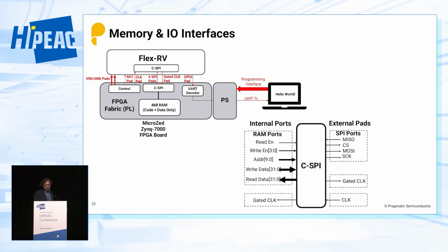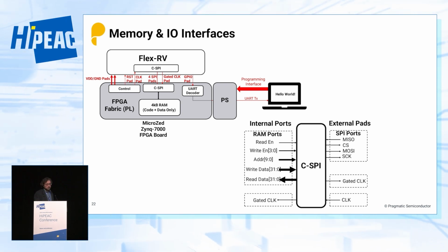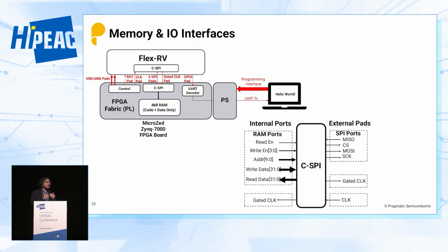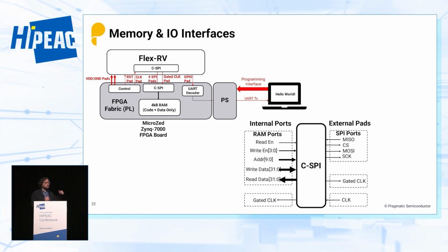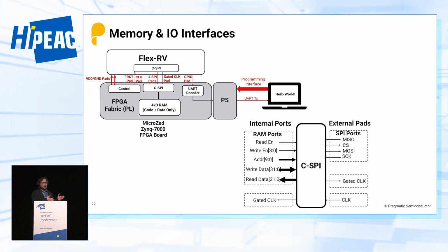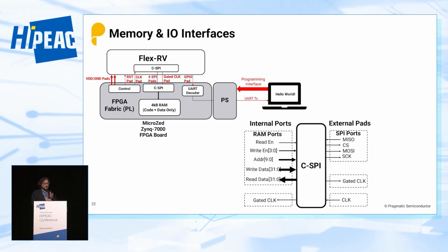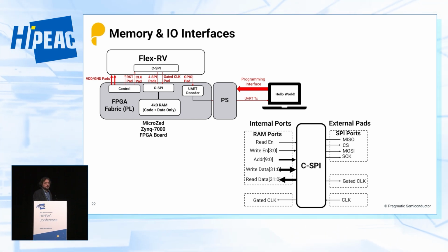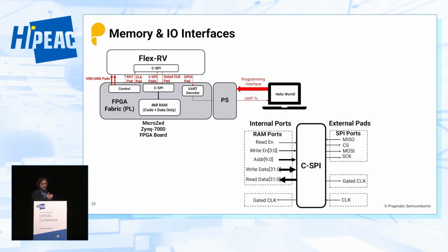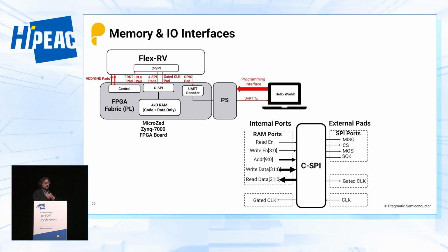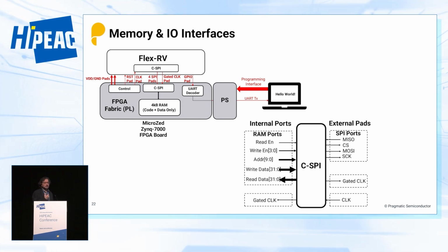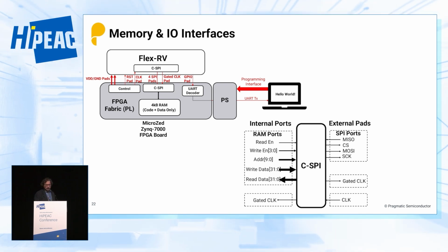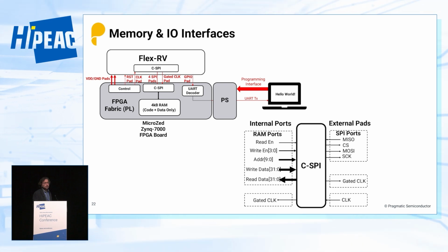So very quickly, this is how it works. When we build the chip, this is how we test it. We connect it to an FPGA. The FPGA essentially emulates the off-chip memory, but also supplies the power, the reset, and the clock, and then gets the GPIO, general purpose input-output, as an output from the processor. This is where we get the running result. If you run a test program, the result comes through the GPIO interface to the FPGA, and is then shown on a laptop.